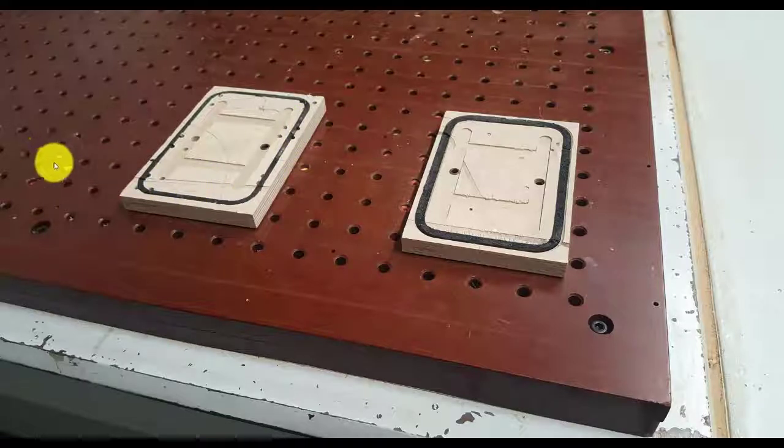But in this case, I want to plug them, because if I just want to sit something on top of these pods in a minute, I don't want suction and air escaping over there, so you're going to plug up all holes that aren't being used. It's probably bad practice in this case to drill out all the holes in the bed of the CNC. You just drill out the holes that you need and plug them when you don't need them.